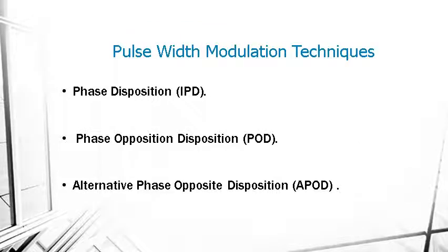Pulse width modulation technique. There is phase shifted pulse width modulation, PSPWM, and a subclass called level shifted pulse width modulation, which includes phase disposition PD, phase opposition disposition POD, and alternative phase opposition disposition APOD.